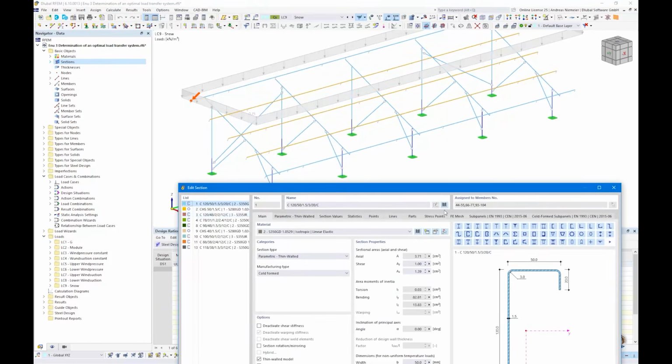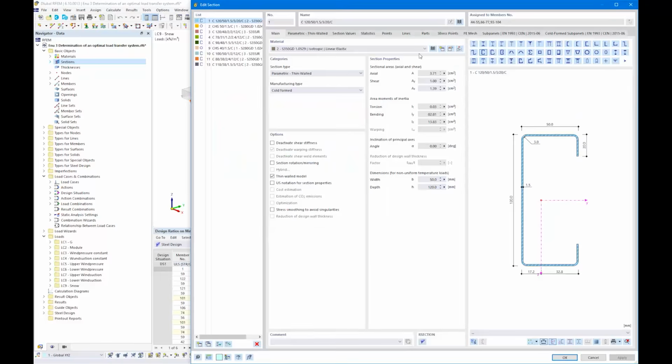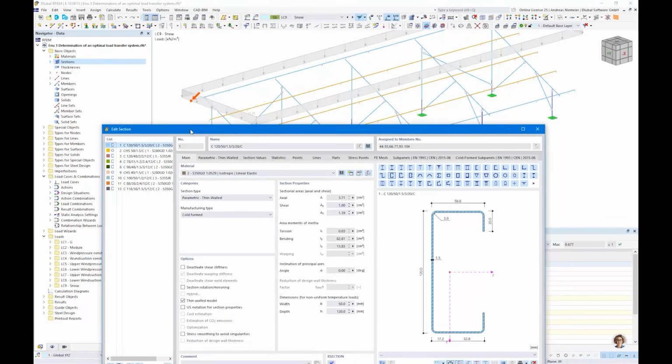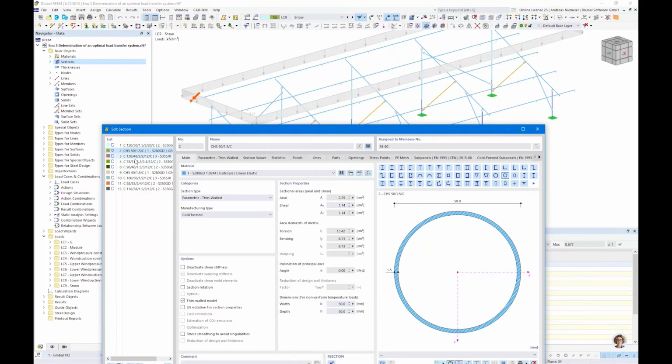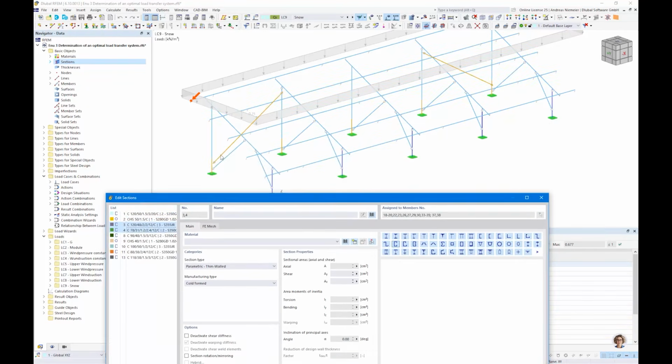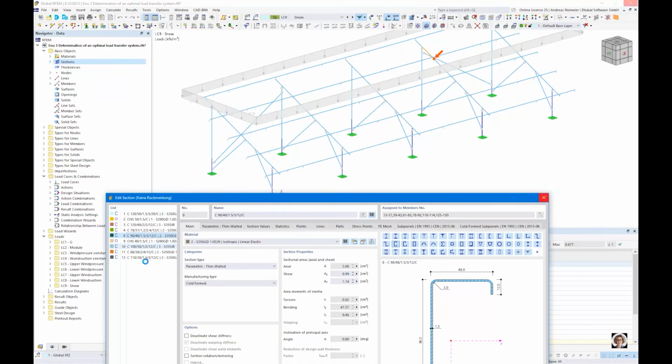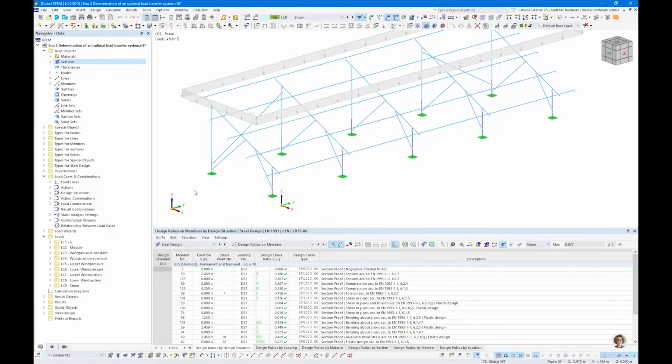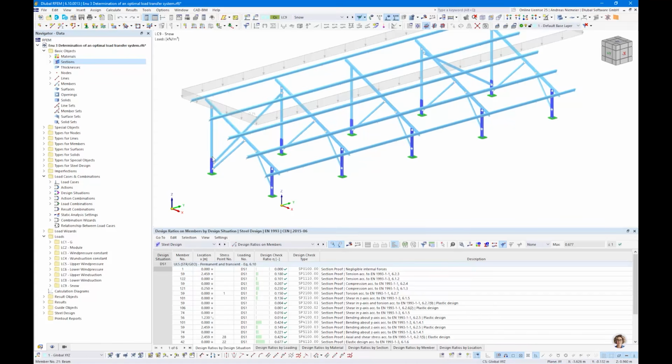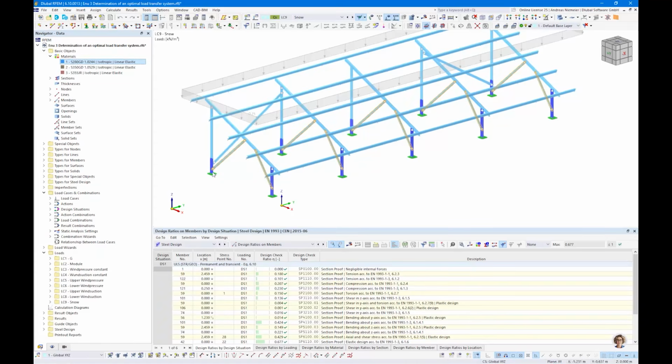used different sections. So how should I do it, maybe... oh no, not like this. So maybe this section, you see it's highlighted in black, maybe this is only the bracing, maybe here only this beam, here the piles, and every pile also has a different, maybe if we look here, material setting. So we have here material for the bracings, material for the upper system, material for the lower system.